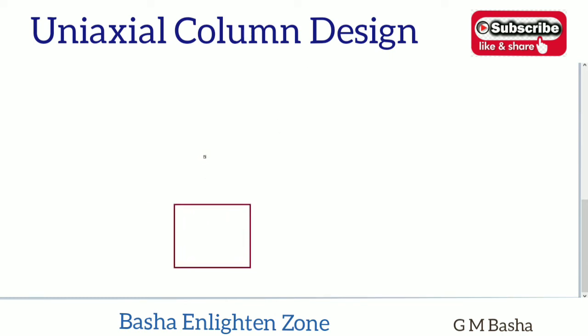So here, this is the cover, and this is the overall dimension taken from here to here, that is 600 mm, and here to here, the cover is taken from the center of the dia bar. This is the lateral tie of 8 mm.